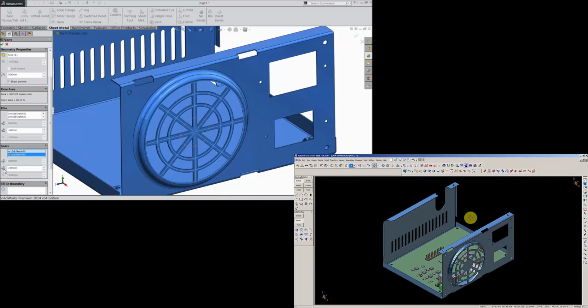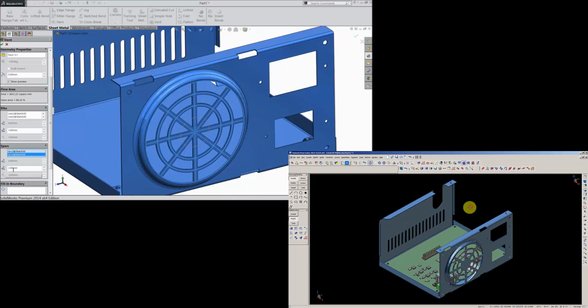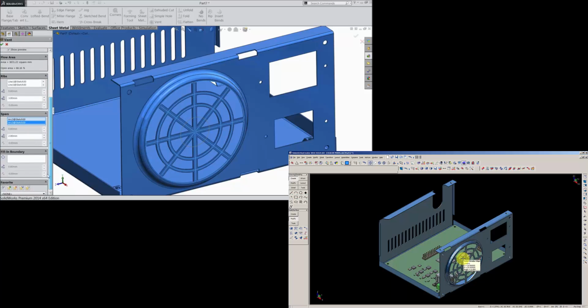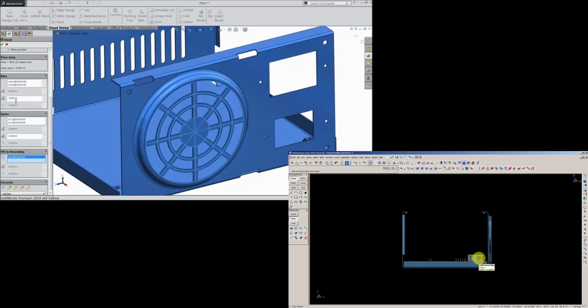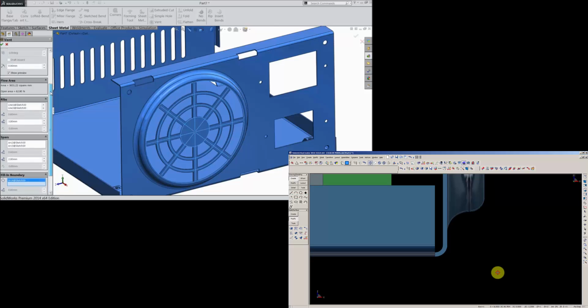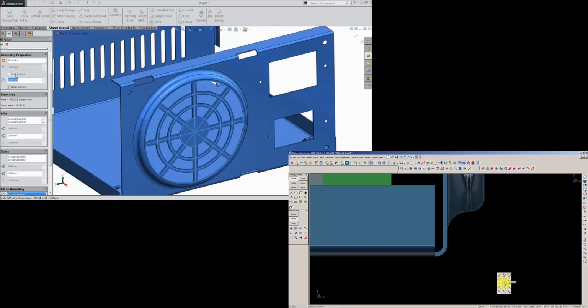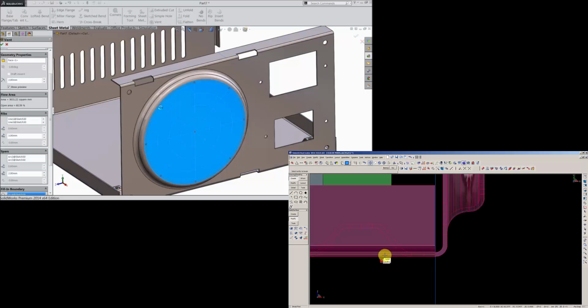OK, and keep the width 22 mm only and select the fill boundary, the last one, and here select radius, keep 2 mm radius. See, this all become 2 mm. Select OK.